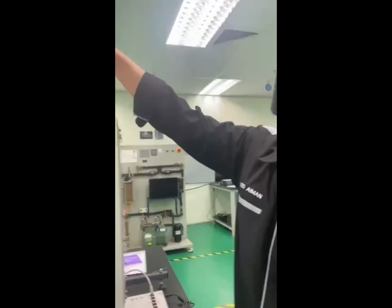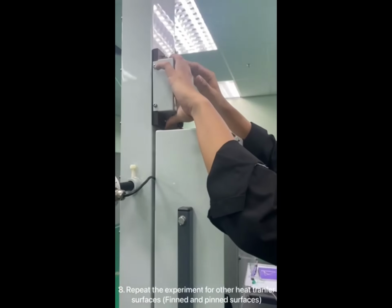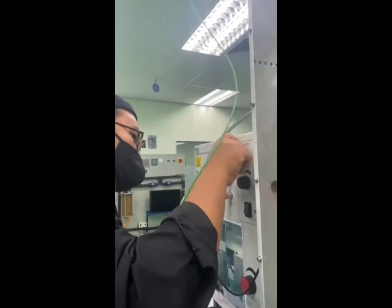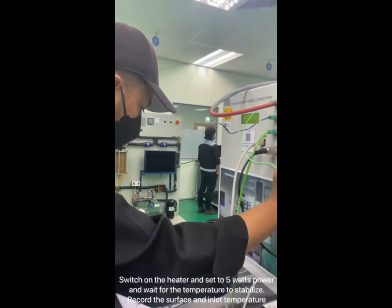Okay, that's all. Repeat the experiment for the other heat transfer surfaces, fin and pin surface. Next, for table 2, repeat step 1 to 4 in the fixed power experiment with pin or fin surface.